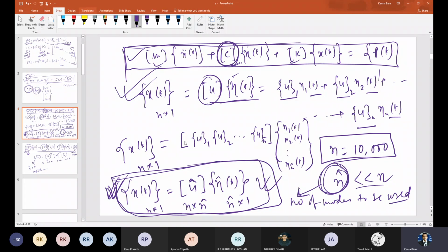You can check it: take a 3 degree of freedom system, and see how much your first mode contributes to the response, or just consider the first two modes and forget about the third. Then you will see that the first few modes are really very important.